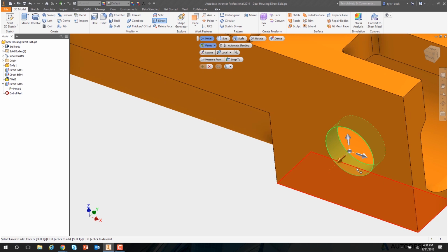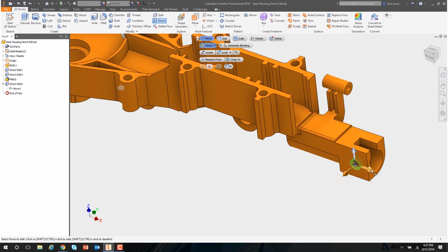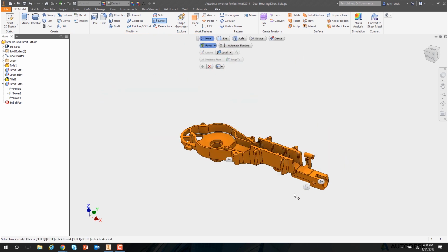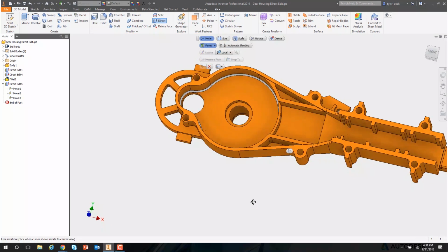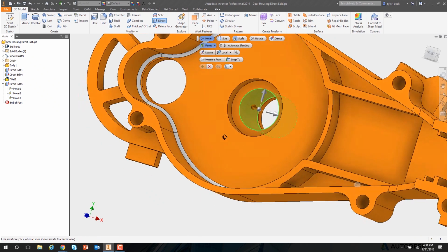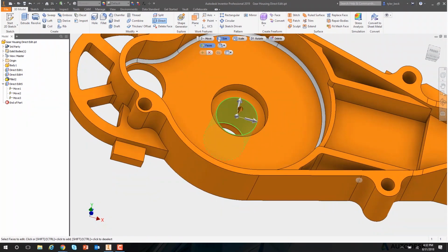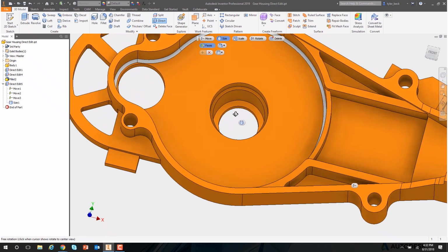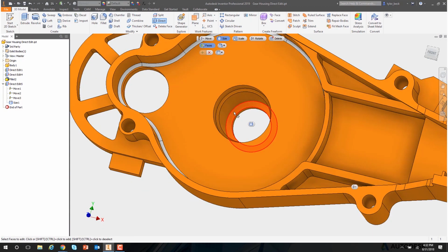This hole is not in the right place. Realign that. I'd like to stretch this face a little bit by 5mm. Put in 5mm, hit OK. What about the size of this interior hole? Maybe we want to change the offset of this hole. Select the face, go to the sizing. We can bring it in, or we can enlarge the hole by a value, hit apply. We've got a new offset hole applied.